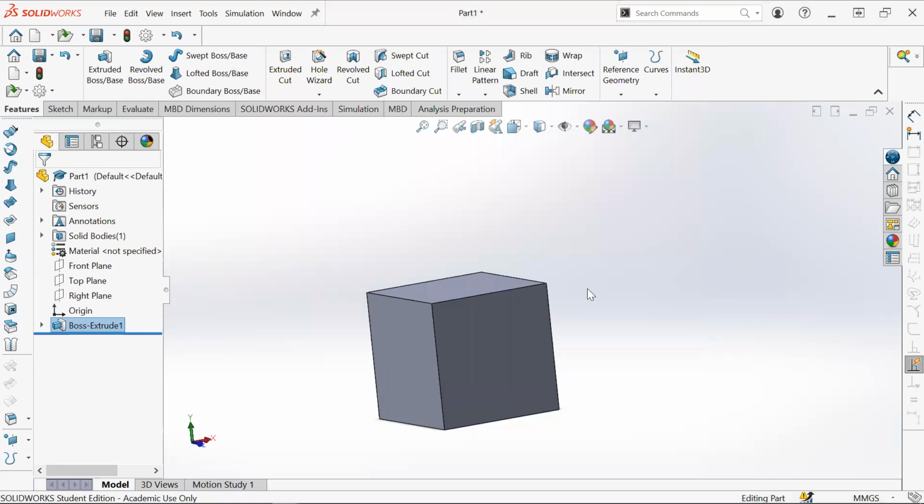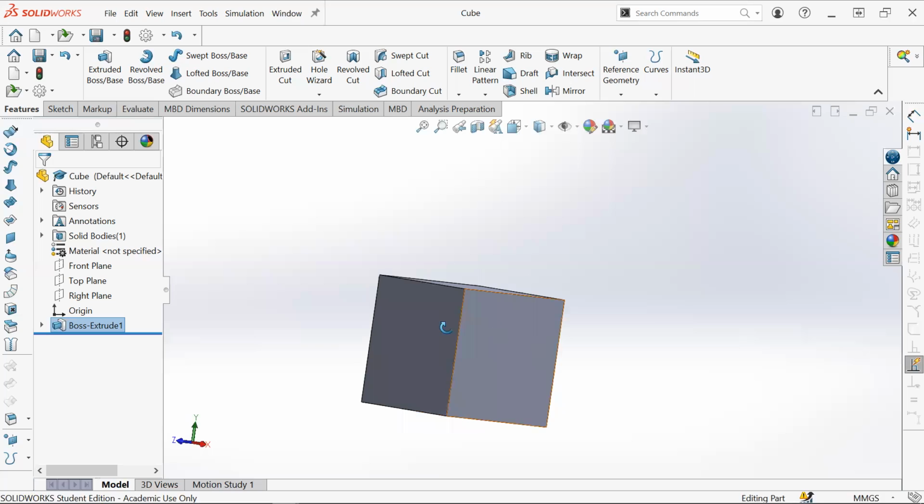folder. Try to make a folder for your simulations. It's honestly very useful because saving your simulations will result in a lot of different other files being saved into your folder. So if you don't save your simulation part or assembly file in a different folder, your main folder is going to be saturated and overloaded with a bunch of simulation result files that you can't really open, but SolidWorks needs to retain the results. So if you double click on an old assembly that you've done simulations with, all those simulations will be saved, if you keep those extra files that SolidWorks saves in your current folder. So you'd want to save your simulation part in its own folder or in a designated folder where you put all your simulations in.